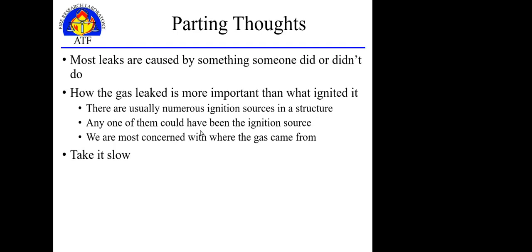One thing that crossed my mind from the standpoint of differences in gases, for the most part, you're not going to see much of a difference between propane and natural gas. I've heard people say that, well, this caused way too much damage to be natural gas. It has to be propane. And frankly, there's not much of a difference when you're at that perfect mixture where you're toothpicking the structure. They're pretty much going to be the same. But on either the upper or lower ends, maybe there might be a bit of a difference.